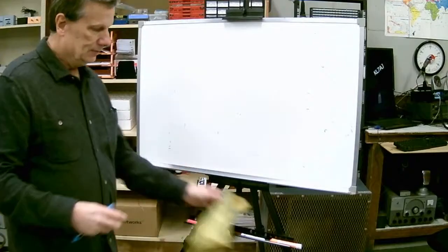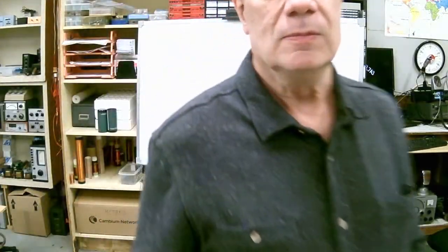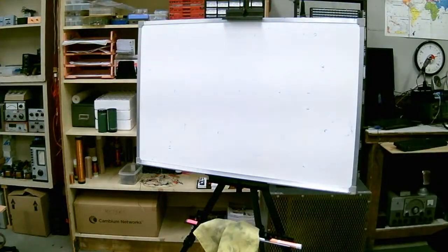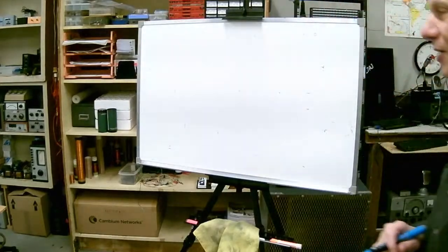Oh, and if the antenna's too long, the relationship between voltage and current is going to swap the other direction. The current would come first, and voltage would follow. It always works, whether it's lumped constants or continuous antennas.